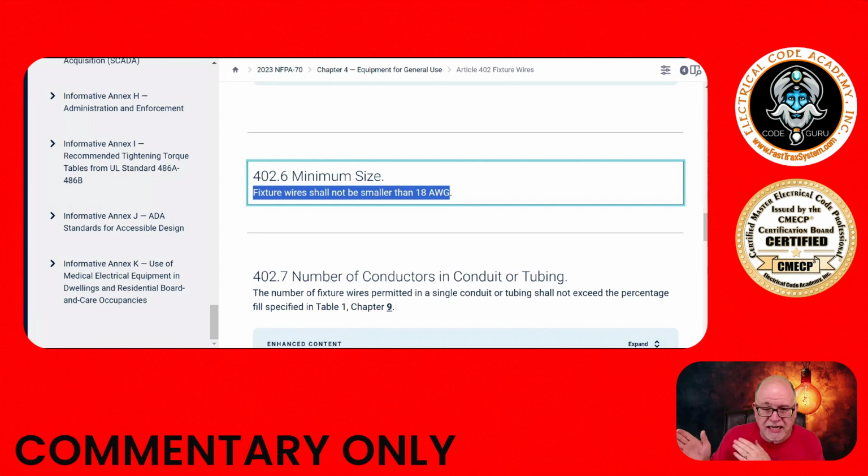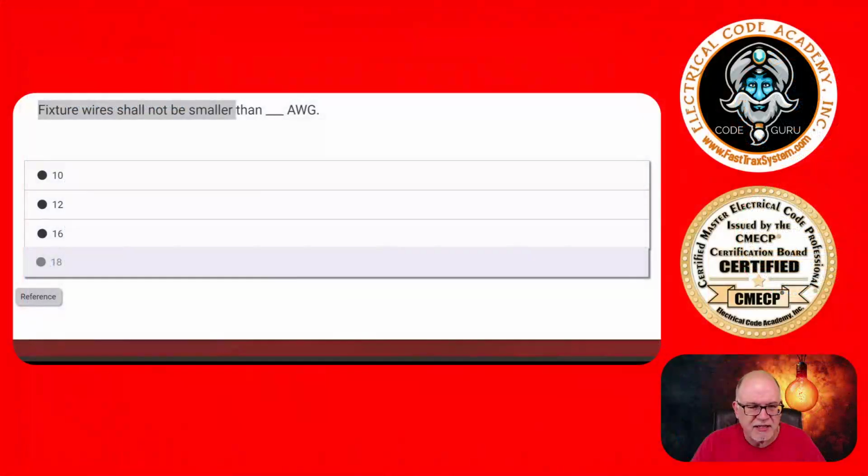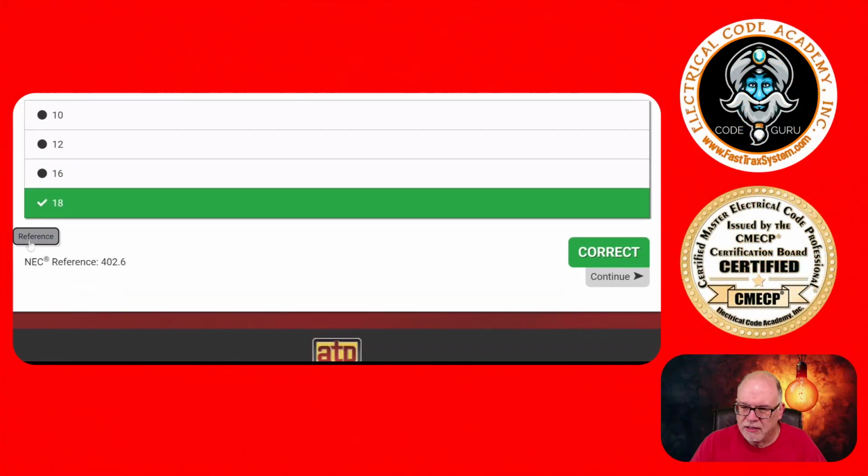You could have gone to the index. You could have spent some extra time there. This is why I tell you the difference between a structured program like ours is you learn the size of the articles. It just happens. This is why in our program we send you back and forth into the NEC, okay? All right, so we'll come back to the question. Obviously, it's 18 gauge, and there's your code reference, 402.6.